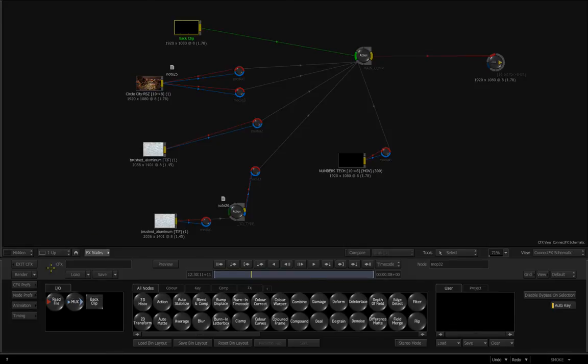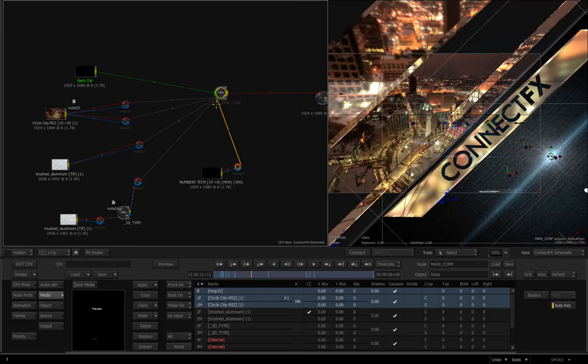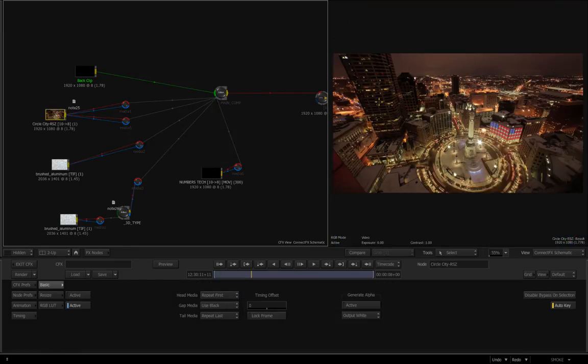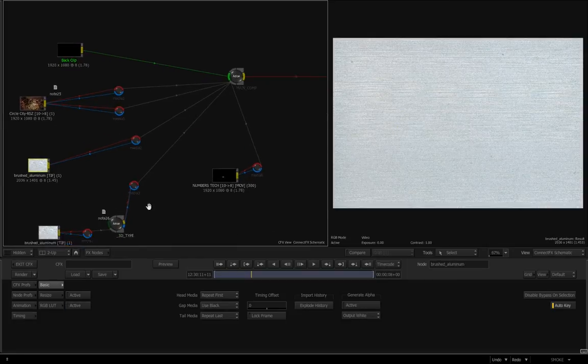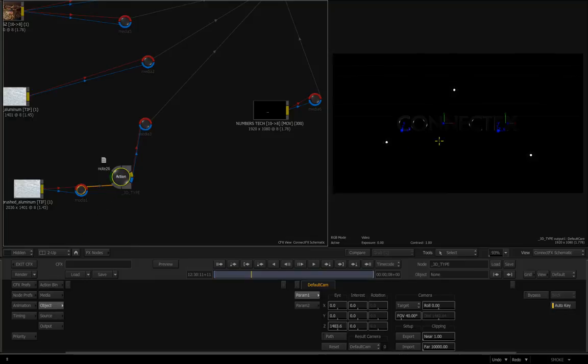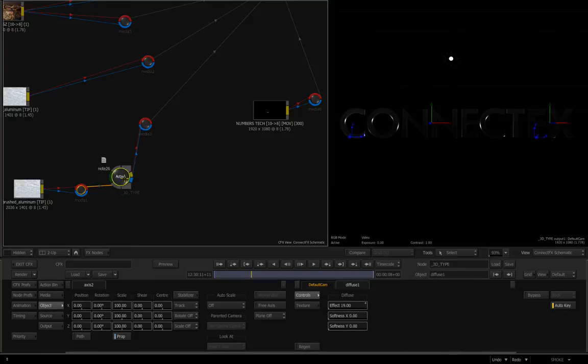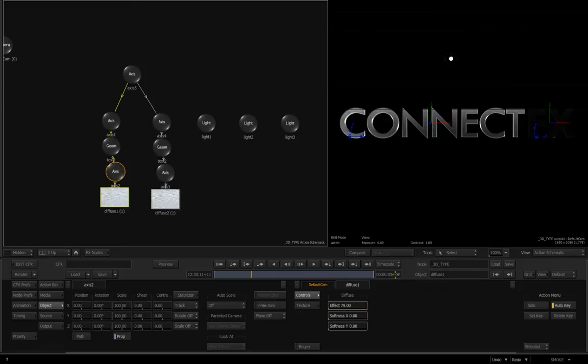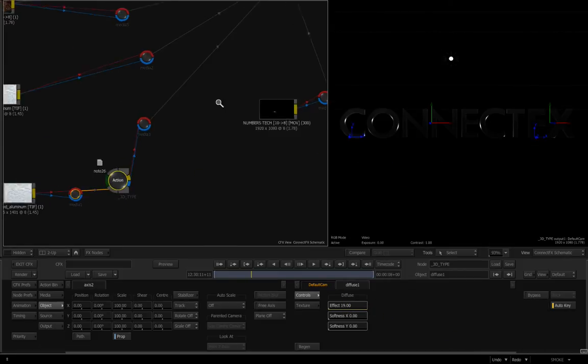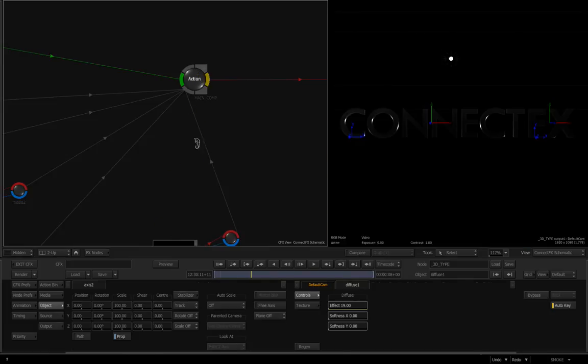If we go to 2-up view, you can see we have our action set up, which is using one video clip, our brushed aluminum texture again, and another 3D text action node for our text creation. If we go into our action schematic and look at our diffuse layer, you can see that the effect has been dialed down all the way to 19. If I bring it back up, you can see that our silver texture returns. This then all feeds into this main action comp.